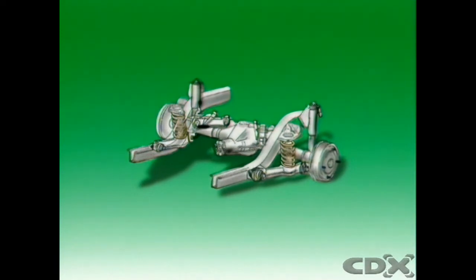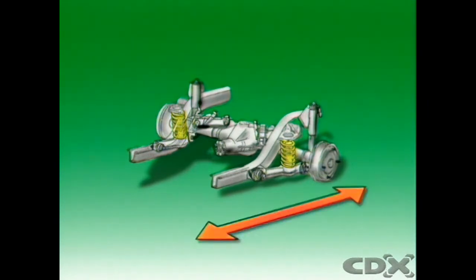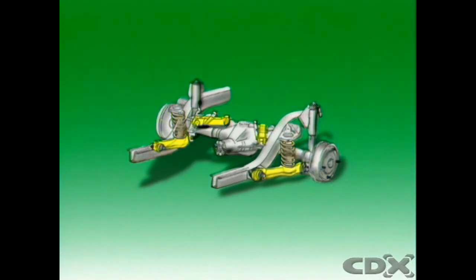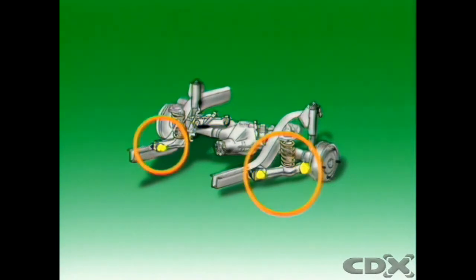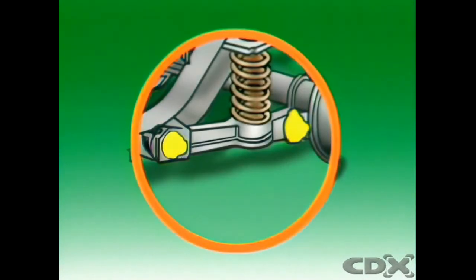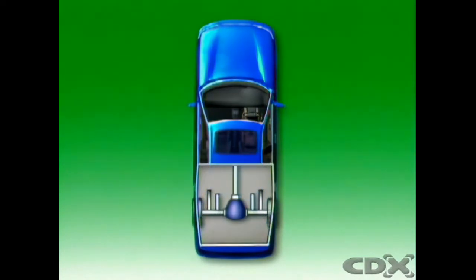This rear-wheel drive vehicle has coil springs in the rear suspension. Therefore, special provision must be made to locate the axle, laterally and longitudinally. Trailing arms or control rods are used to position the axle longitudinally. They have flexible rubber mountings at each end where they locate on the axle housing and on the chassis frame. They would allow the axle to move laterally if it were not restrained.